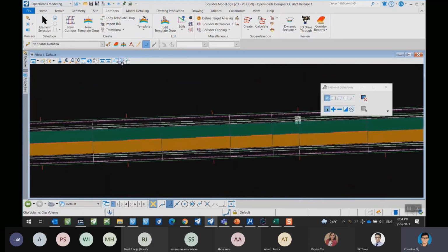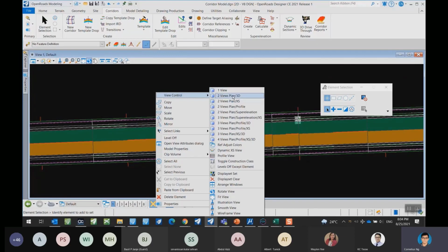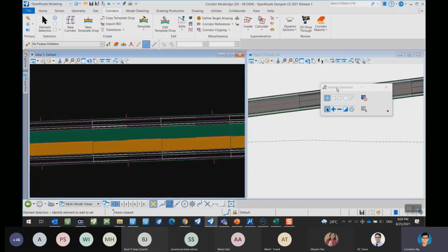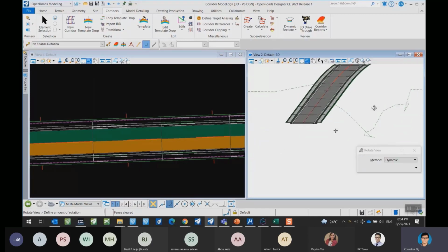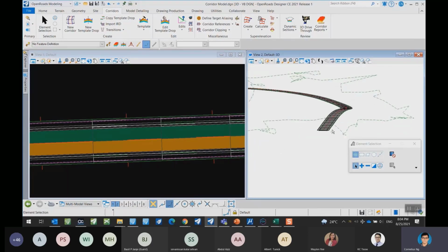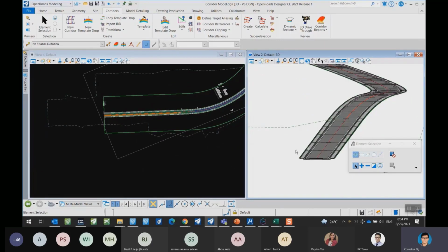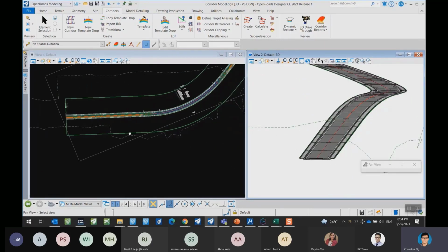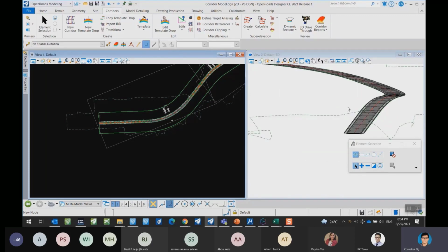And then you can see that in the 3D now, if I were to bring out the 3D model, view control, views plan / 3D, I would have the road cross section. But something is not right, isn't it, my friends? How come this road is created with no slope, cut and fill, nothing whatsoever? And it's definitely not because it is very close to the surface, because we know that there's a huge amount of cut and fill based on my design profile.